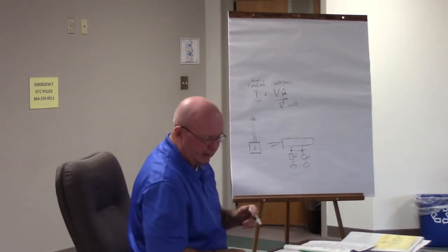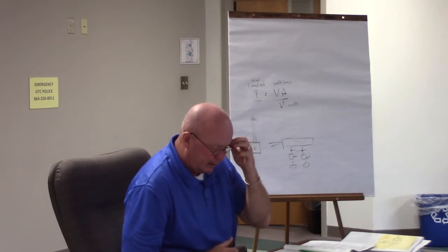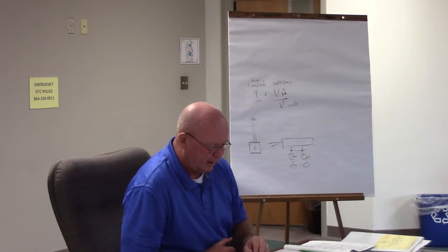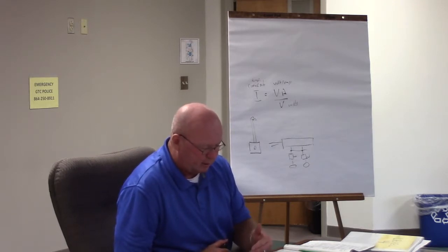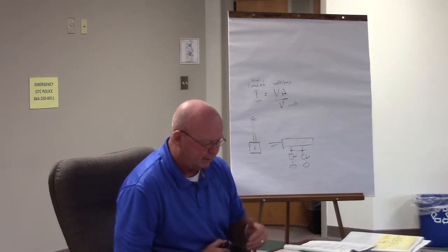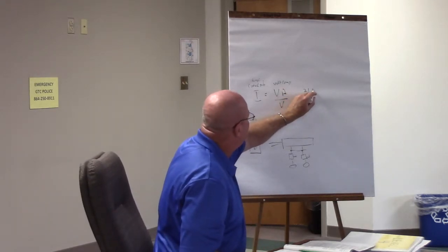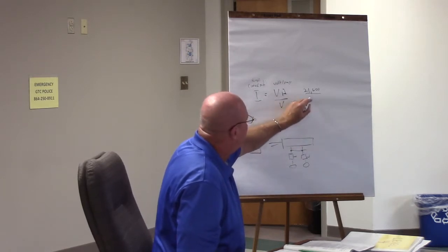If we look on page 7, it gives us an example, and it's single phase now. Single phase, that's important. For example, the ampacity of a single phase 240 volt load, that's our V, rated 21,600 VA, or volt amps, is determined by dividing. So we've got VA as 21,600, and our volts is what? 240.